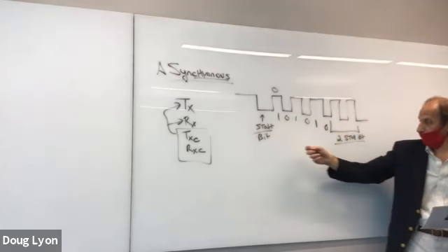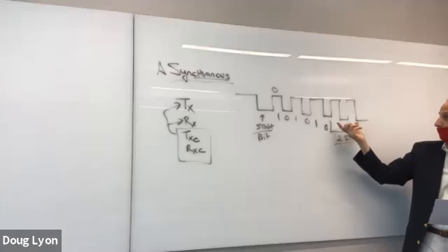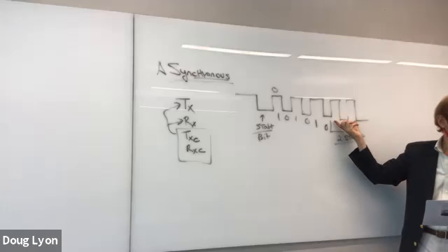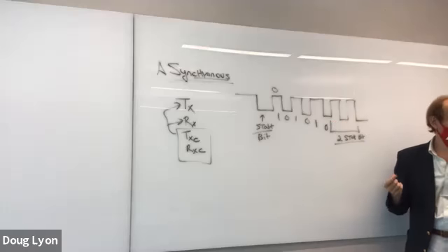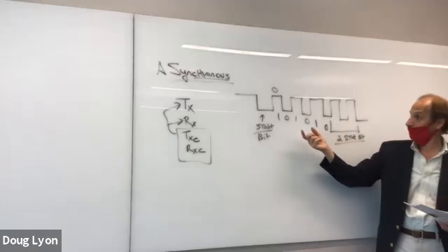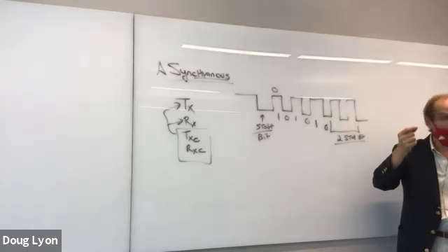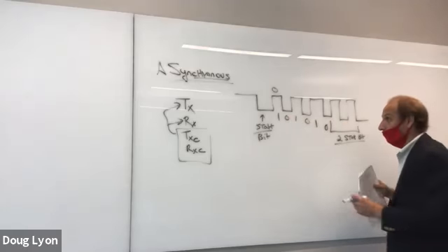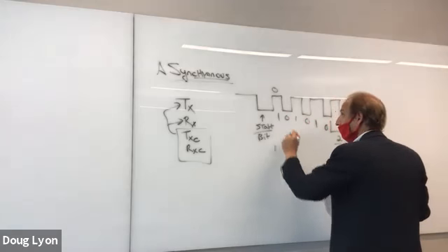The start bit and the 2 stop bits are your framing bits and your synchronizing bits. These signals coming together allow you to resynchronize the internal clock in your receiver. So your asynchronous communication interface adapter, which could in theory be built into your CPU, is effectively looking for these pulses to come together so it can determine the timing. Because the most important thing that you must have here is a regular sampling signal that comes in, let's say, in the middle.